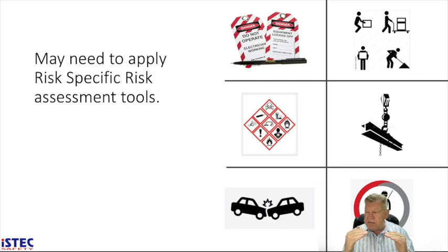In each of these categories, whether it's explosive, flammable, whatever, how probable is it that this will happen? And if it does happen, how great is the risk? We also need to understand, if it's toxic, does it get absorbed through our inhalation, through our breathing, or through our skin contact? Absorption. That is an example of the kind of questions that we ask when we do hazardous chemical substance risk assessment.